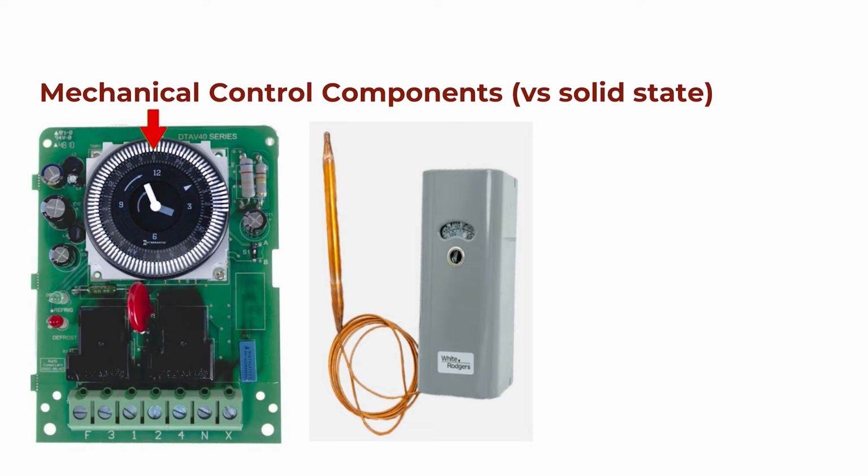where you have a time clock. We all know what clocks are. And we have these pins that represent 15-minute intervals that we can set a defrost time to. And then we may have a thermostat, something like this, that will provide our early termination set points for killing the circuit to the defrost heaters early, and then providing some time delay for the fans to start back on.